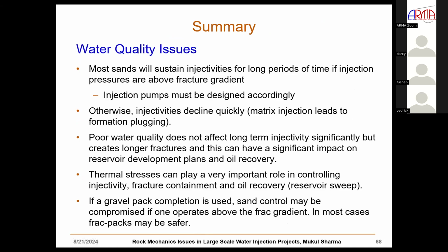So just to quickly summarize what I've already said, most sands will sustain injectivities for long periods of time if injection is above the fracture gradient. Now, obviously, you can't inject above the fracture gradient for the bounding shale. You can only inject above the fracture gradient for the sand that you're injecting into. That's just by the permitting requirements that you'll have, right? So injection pumps can be designed accordingly.